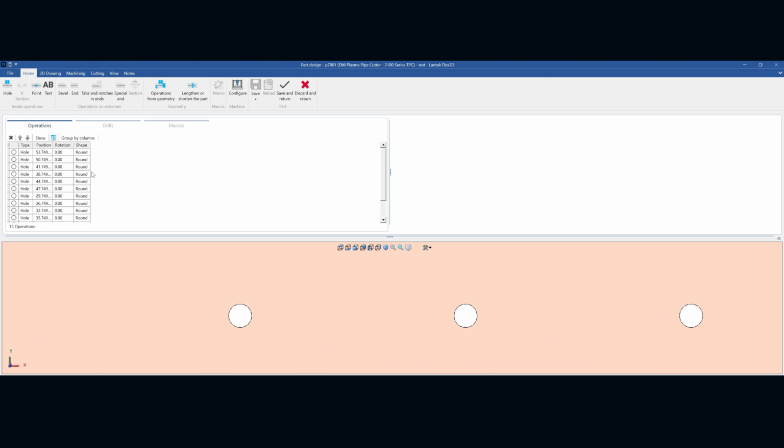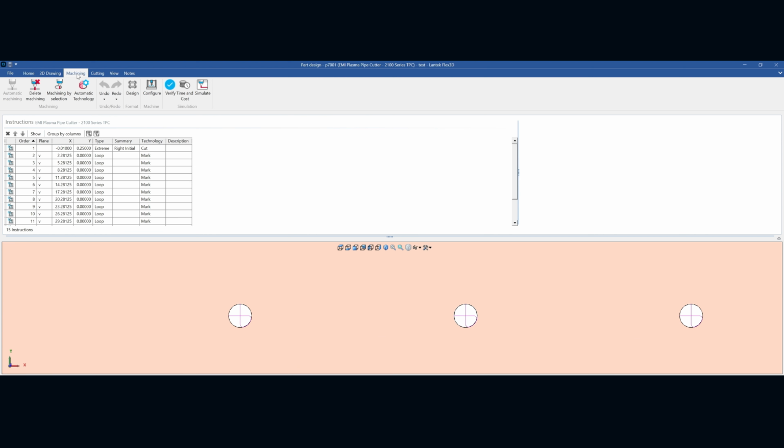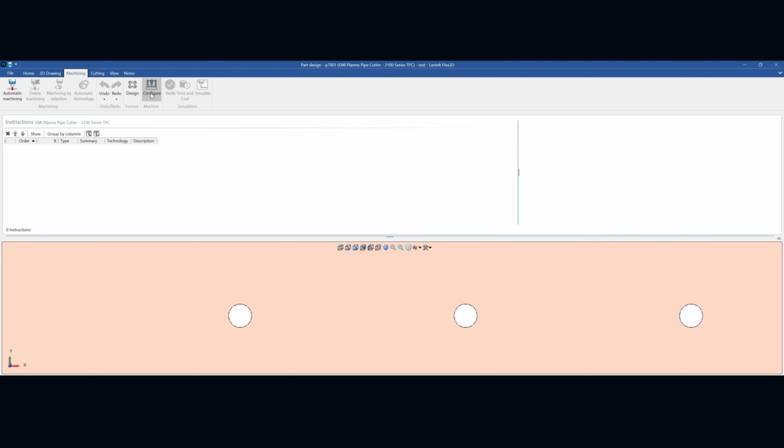This result can be achieved not by changing the feature, but by changing only the tool path. With crosshairs in the center, the part can be center punched. The hole size can also be determined by measuring the radius. We will now delete the machining. Normally, a tool path would be visible circumscribing the hole, indicating the cutting line.